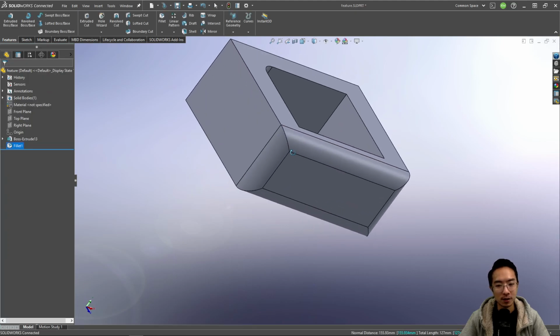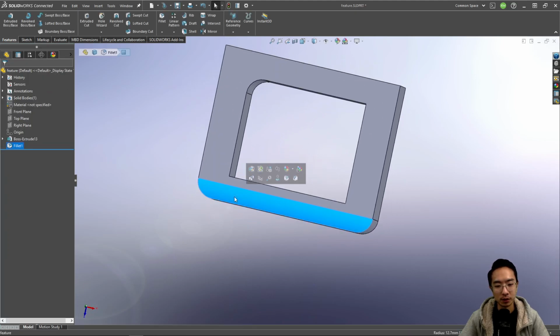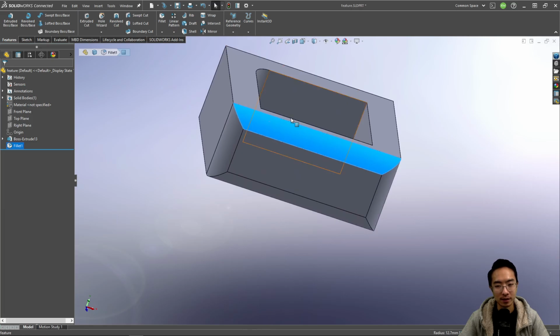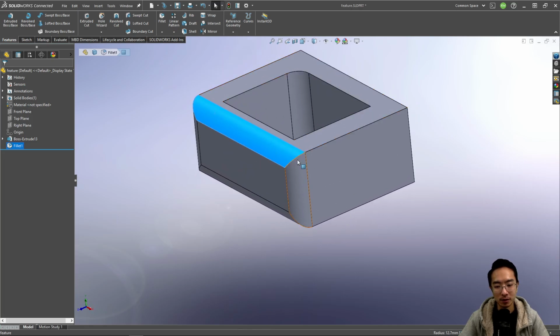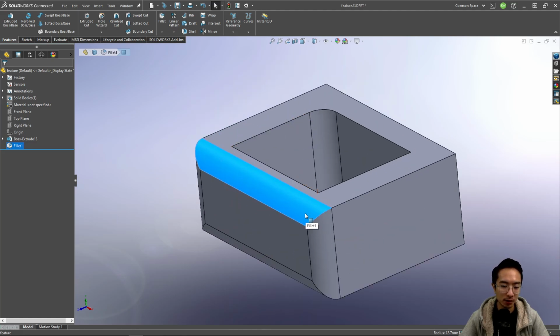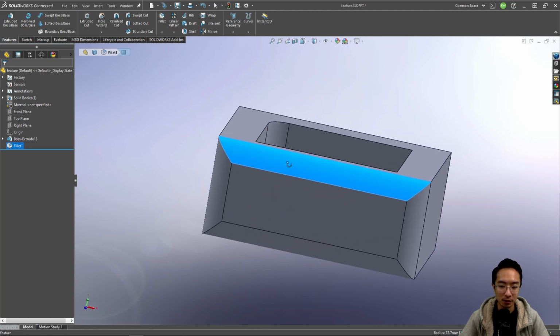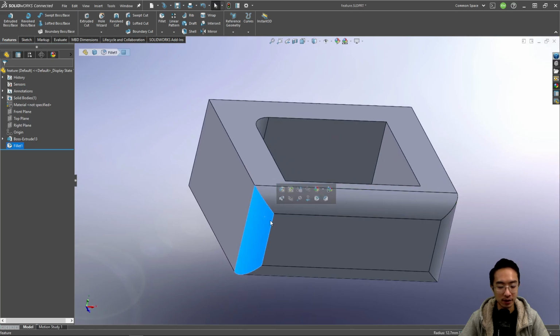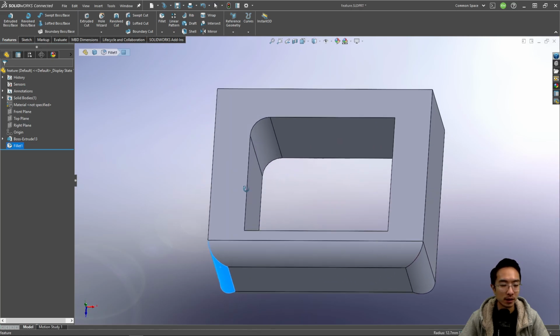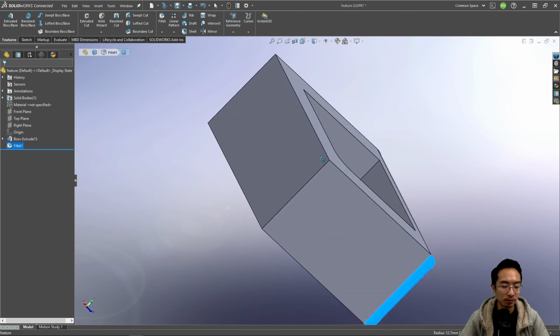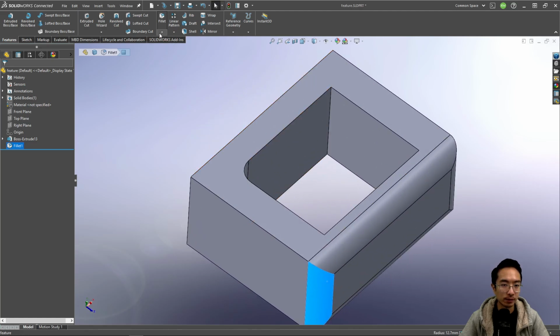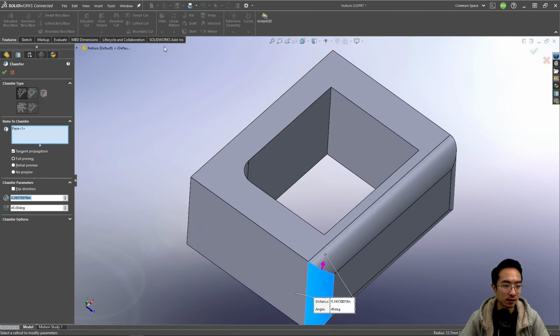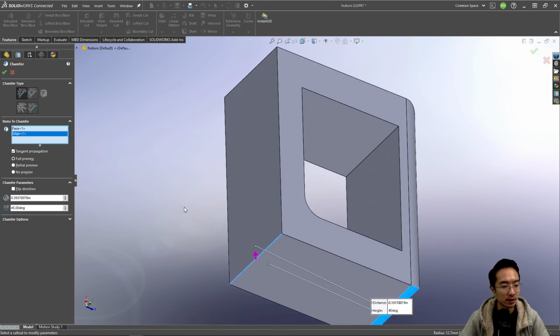Okay, so you really only want to do this if it's for aesthetics, like if you're 3D printing, or sometimes if you're doing injection molding, certain parts need to be removable, or maybe it's just for certain cases where you don't want it to be sharp. But for other cases where it doesn't have to be round, and you don't care too much about aesthetics, you could use a chamfer tool. So you could chamfer this edge here, for example.